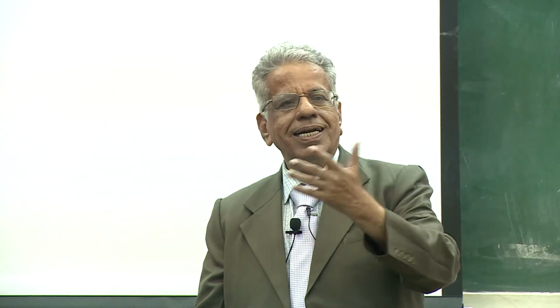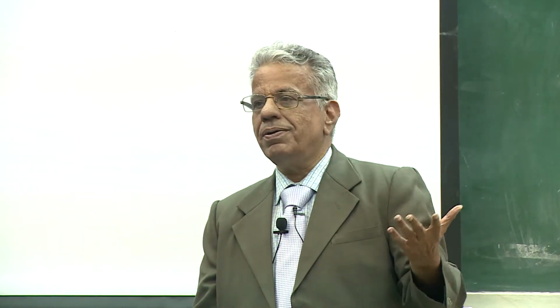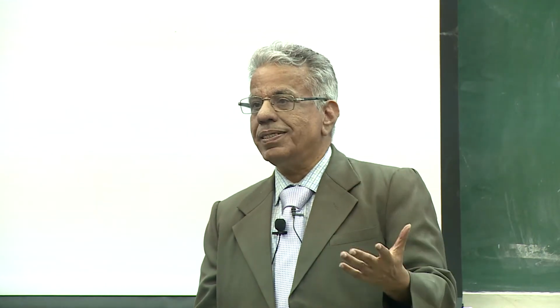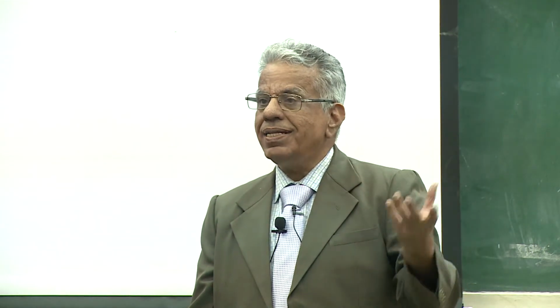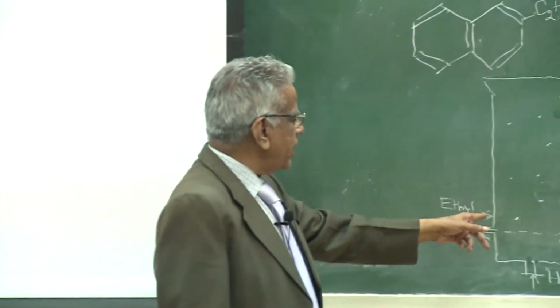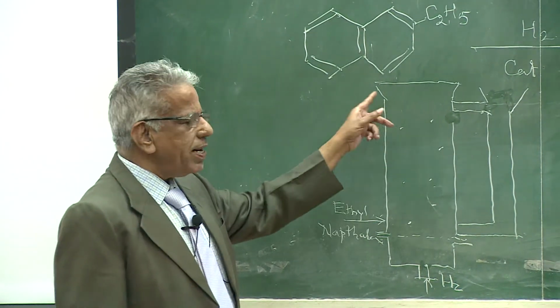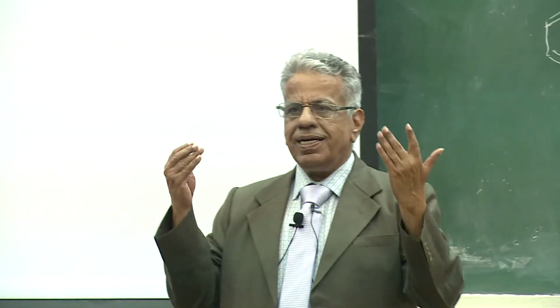So, out of all these steps for a gas-liquid-solid catalytic reaction, which one is rate controlling, and if 2 are rate controlling, 3 are rate controlling, if all of them are participating in the overall rate of reaction, depending upon local partial pressure, local holdup, local concentrations, local temperature, local pressure, how to write the overall rate at that point, so that in the total reactor I know the rate here, I know the rate here, I know the rate at every point within the reactor, for every liter in the reactor I know how to write the rate.